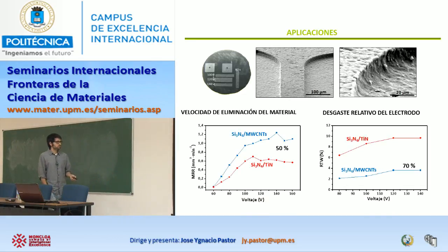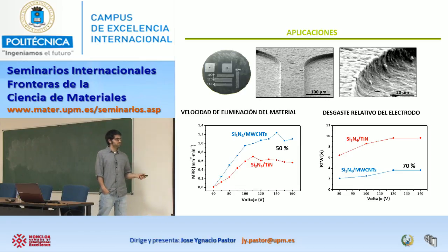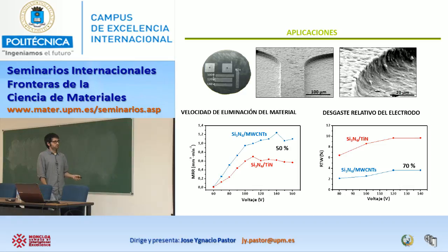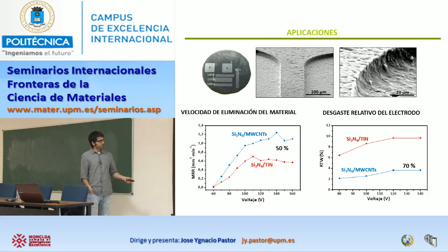Okay. But it's not only that, because we then compare our material. Well, this was a collaboration with a Belgian group. We compare the material removal rate, the velocity at which you remove your material, comparing our material with the material that companies use, the silicon nitride containing titanium nitride. With our material, we even improve the velocity of this process by 50%,